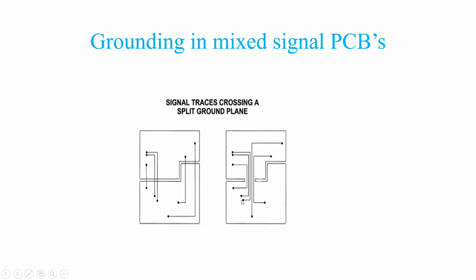If you route the signals on a split plane, the signal impedance will be discontinued over the split area, and all the traces here have been designed for transmission line. The transmission line impedance will vary. Therefore, the PCB designer has to take care while routing these tracks and while doing the signal integrity analysis. He has to control reflections, ground bounce, and simultaneous switching noise in the PCB.